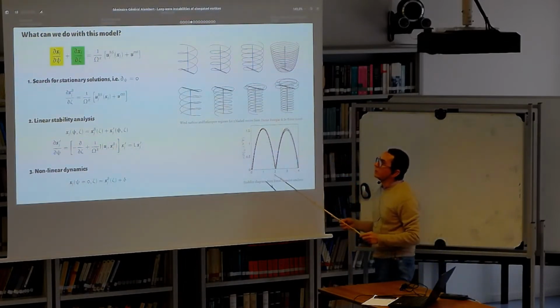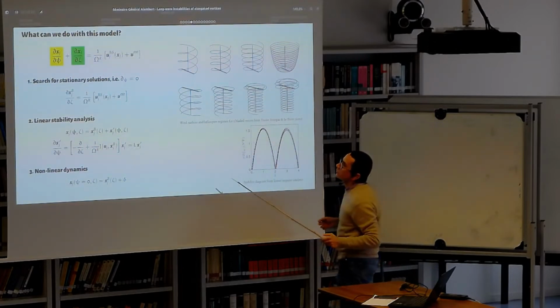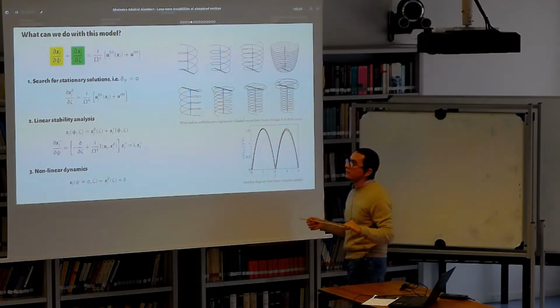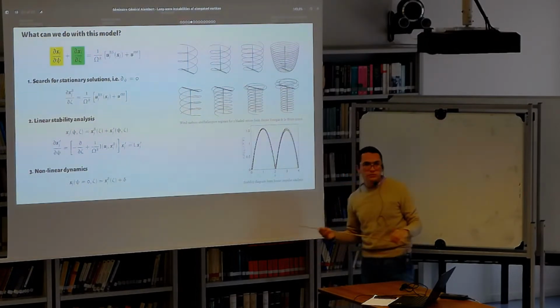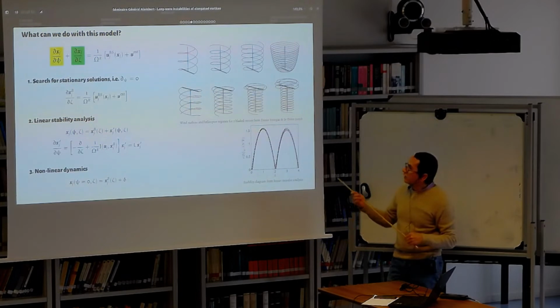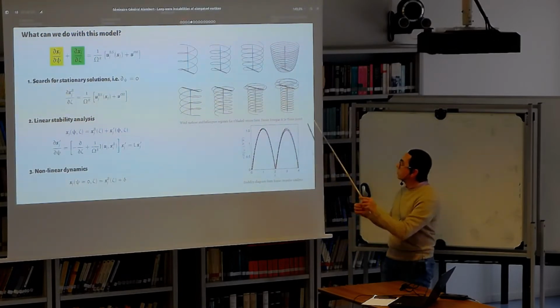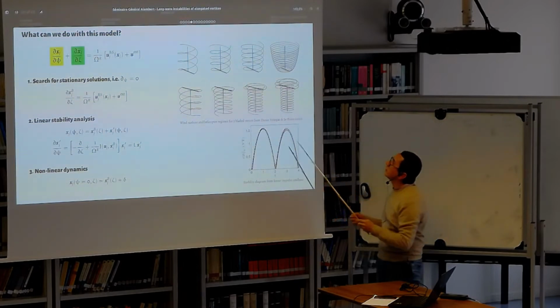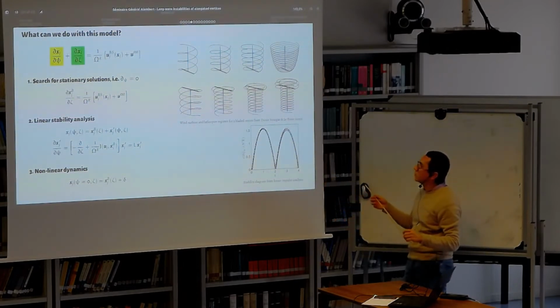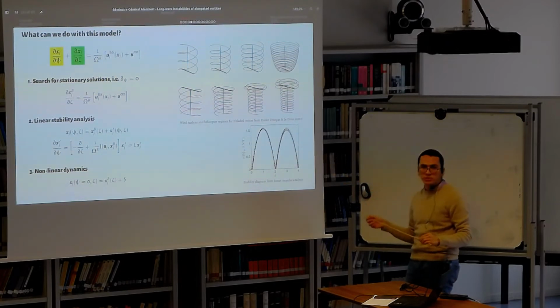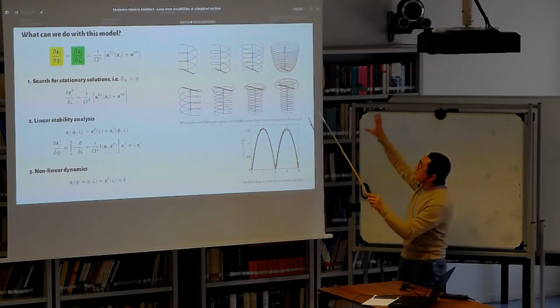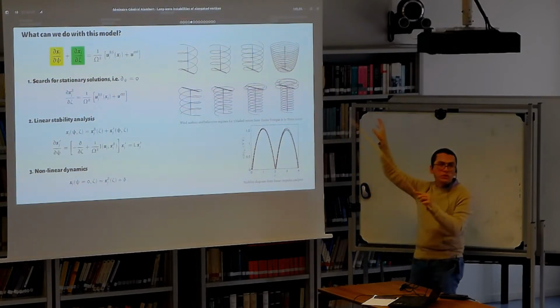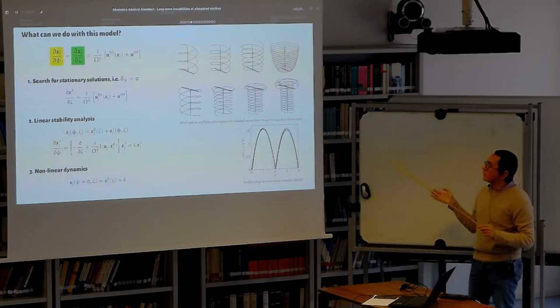First, if we search for solutions with the time dependency zero, we can search for stationary solutions. And like was done by Eduardo and Stefan for the case of two-bladed rotors, they were able to characterize the wake for all regimes, for all wind turbine and helicopter regimes. And in these cases, the whole system is characterized only by the geometry of the planes. This is something that you can't really do, or it is very difficult to do otherwise.